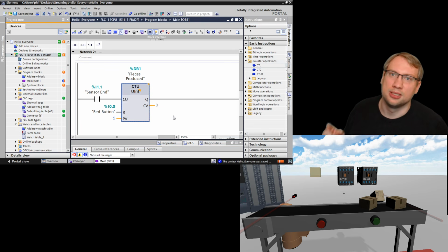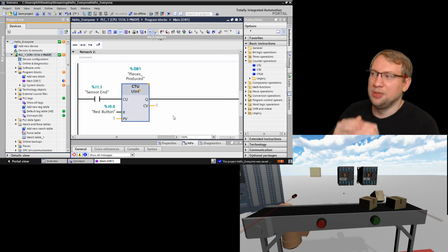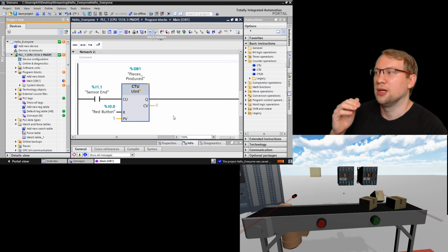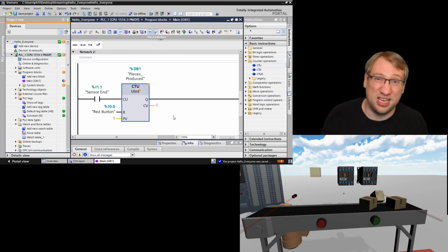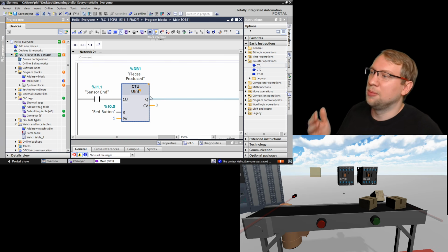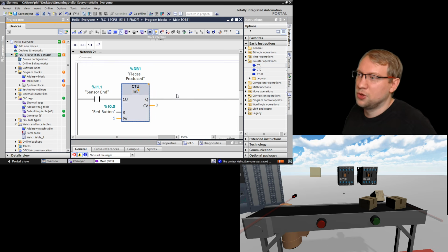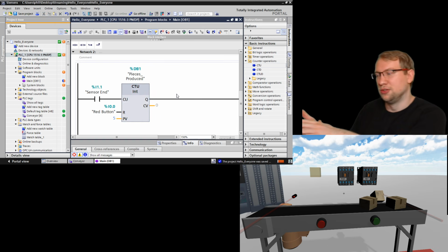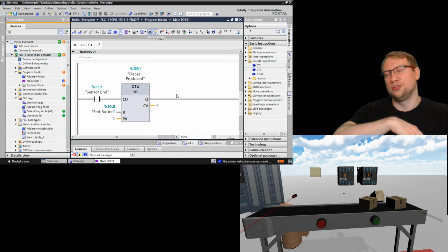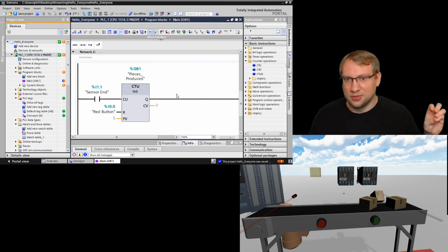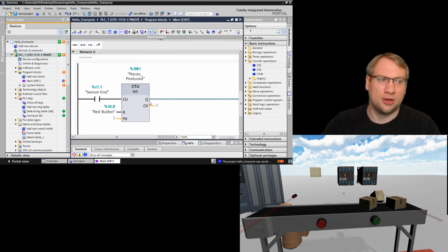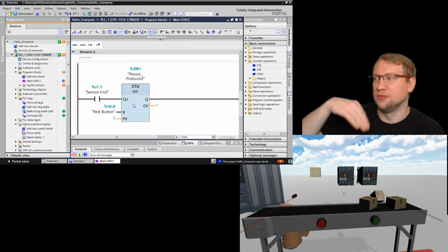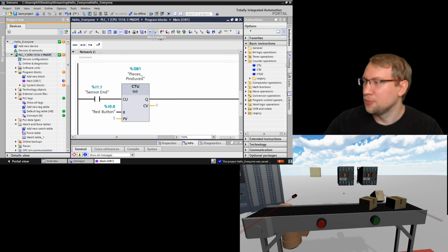U means unsigned, meaning you cannot go in the negative area, so you have to be careful which data type you take. I usually leave it at int, because int goes from minus 32,000 something to plus 32,000 something. So yeah, it could have been a data type. Usually this counter also counts to negative if you take a count up and down.